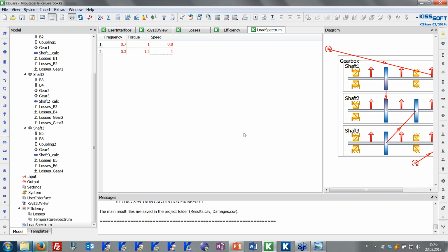Is there a possibility to calculate the losses for a certain load, torque, and input speed instead of input power? Yes, the loss calculation depends on the speed and torque defined in the boundary condition. The input power here is just displayed for the balance. It is not a setting.